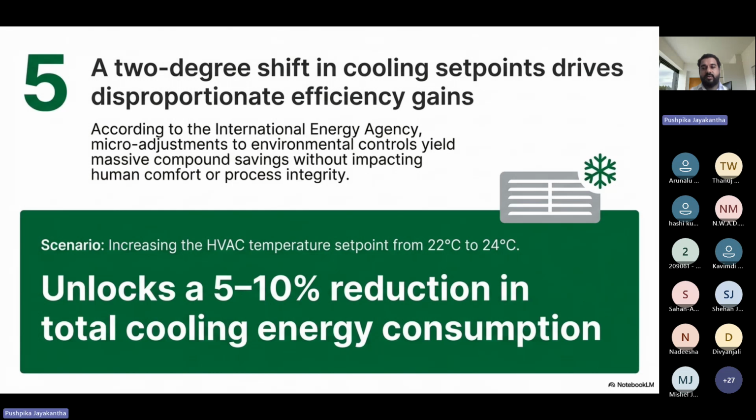Okay. Proper temperature optimization requires accurate temperature controls, calibrated sensors, which is another important one, because otherwise we will not know whether the meters show us the correct figures or not, and then the monitoring of indoor comfort conditions. Those kinds of things you can do to adjust temperature optimization.